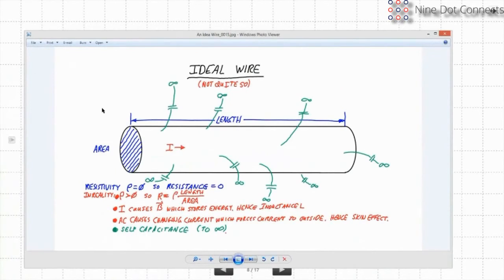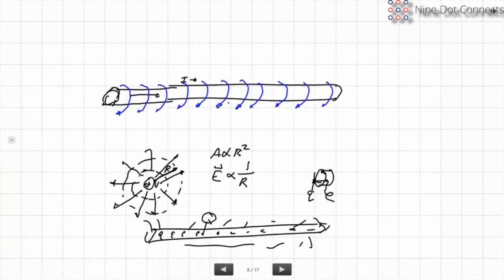All of those things mean that that wire is going to have difficulty passing high frequencies above some point. It's going to have impedance stopping it. It's going to have capacitance that is also trying to short it out. It's like an LC filter down its entire length. So that's something that we really need to understand as we get into talking about high-speed switching things, because the leads coming out of transistors and ICs and things all have those effects.